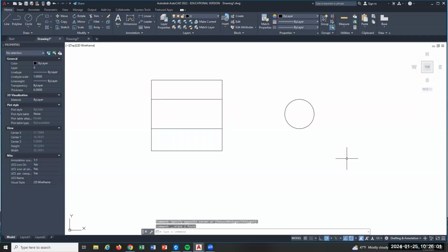But now I have my two lines in projection. So one view will really help you make another view. Draw your front view first and then make your side off of it. Project things over, super easy. Best way to do it. These need to be hidden. Okay, so we're gonna turn them into hidden lines.